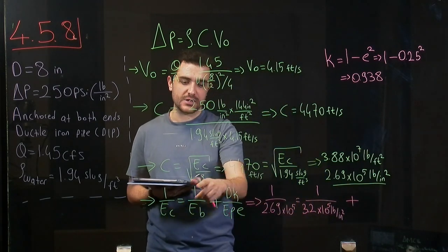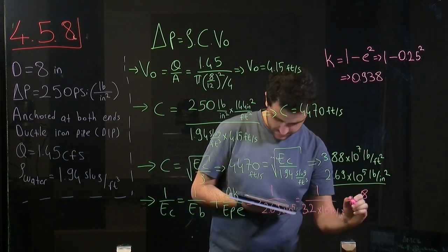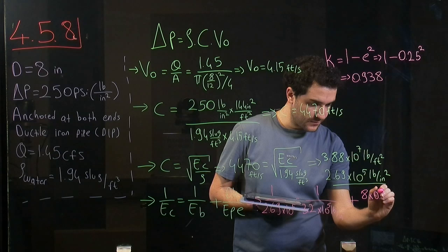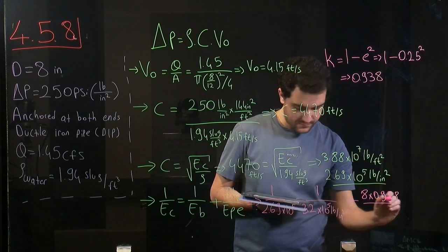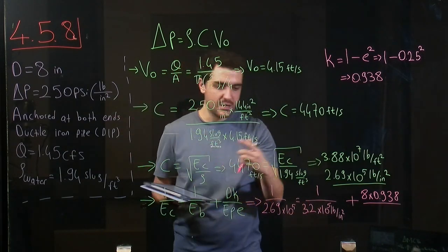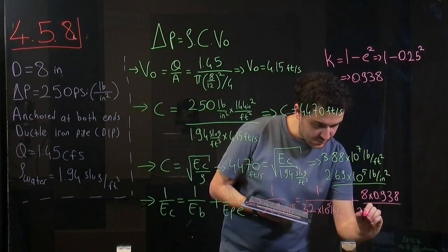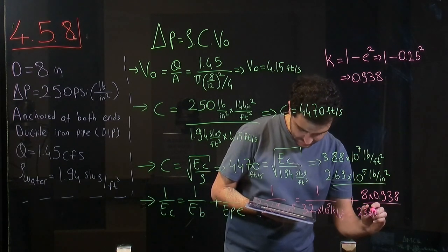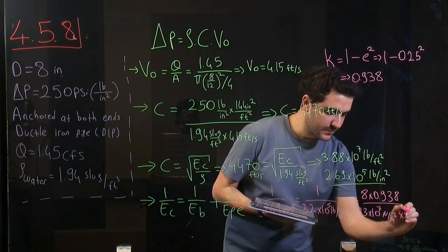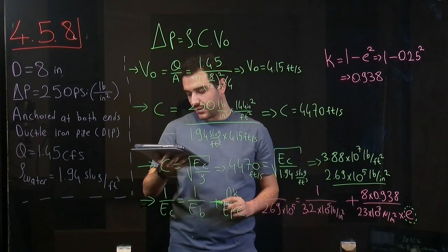This time we are going to use inches because we write everything in inches. We have the K value. And we have EP, which is also not given here, but it is a constant value. You can get it from tables. Times e. And as I mentioned, this is what we are looking for, which is the thickness of the pipe wall.